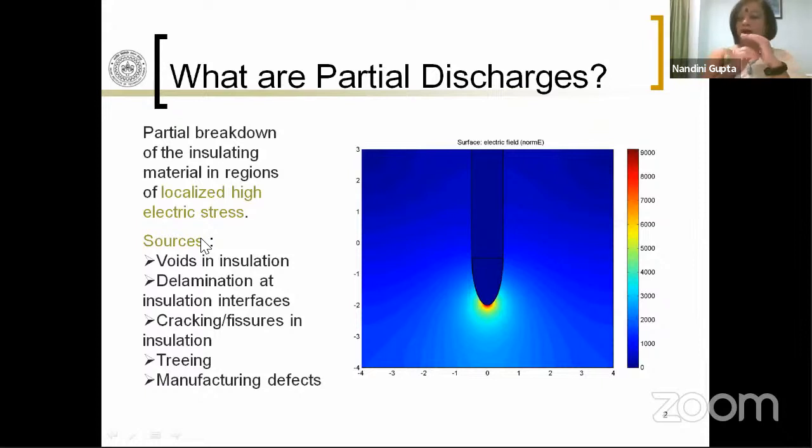So whenever you have a solid dielectric with high permittivity or high dielectric constant, and there is a small gap, the gap would be stressed much more than if there was no solid insulation. Essentially, the presence of a high permittivity material in the vicinity of a low permittivity material tends to exacerbate the electric field in the low permittivity material.